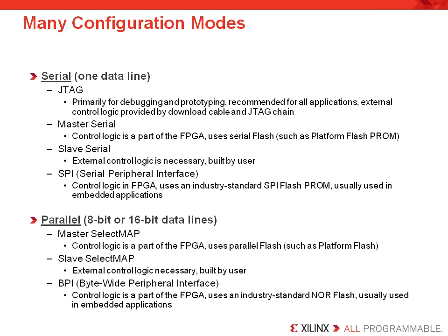The benefit is that this configuration uses a price-competitive SPI PROM rather than another means to store the bitstream. It is also possible to use the SPI PROM to store software code in case the user is building an embedded application. This is a relatively simple configuration scheme to debug since the control logic is already a part of the FPGA.